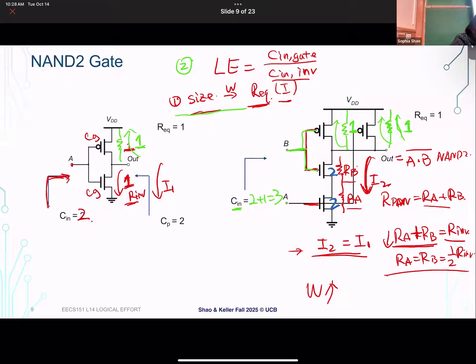Right, so if I look from this node, the gate capacitance I'm connected to on the NMOS is size 2. Size 2 is basically normalized. The input capacitance is 2, so this is my NMOS part. Each input is connected to both NMOS and PMOS. So look at the PMOS, we mentioned it's size 1, so this is the PMOS part. I'm charging and discharging both capacitors there, so we sum those two together, and that's my input capacitance. Are those numbers describing the sizes of the transistor? Yes. How are you going directly to the capacitor?